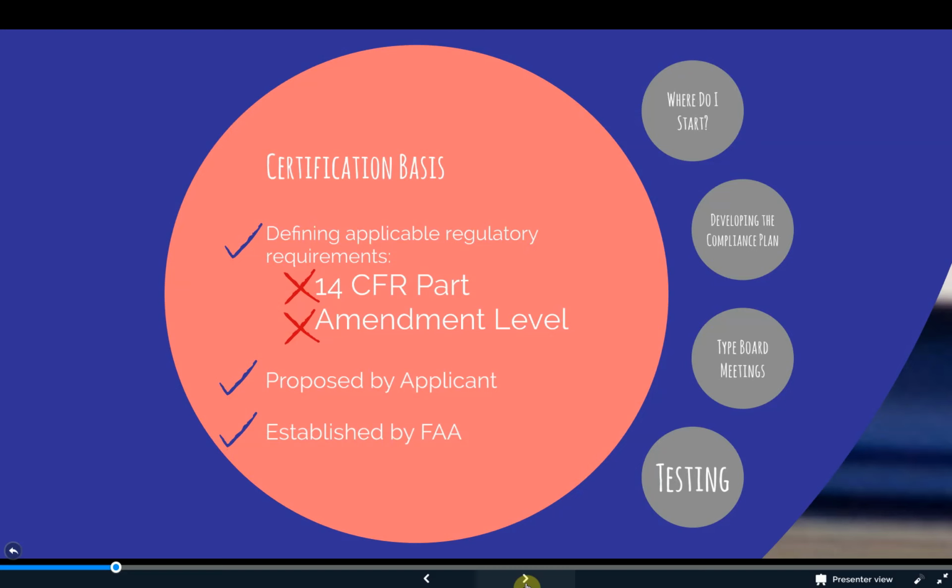The certification basis is established by the FAA and agreed to by the applicant based on a mutual understanding of the design features of the product to be certificated. Upon agreement of the certification basis, new policy will not be imposed unless the policy is needed to address an unsafe design condition the FAA has corrected by mandating a change on other projects with the same design feature. Order 8100.15 defines how the FAA establishes the certification basis, further by explaining that the Project Notification Letter Response, or PNR, provides acknowledgement that the certification basis is acceptable, including any limitations, conditions, or objections.